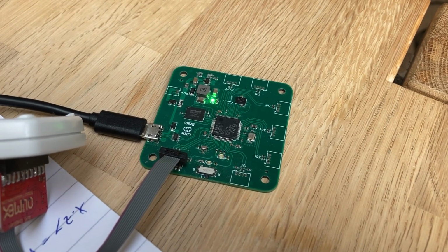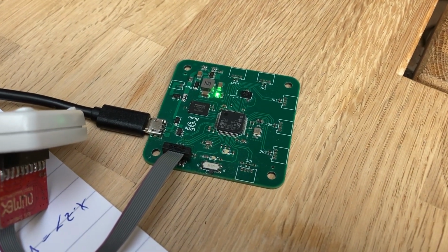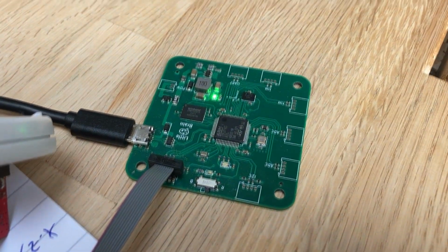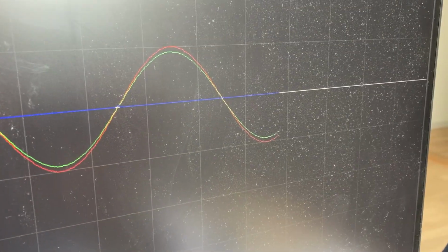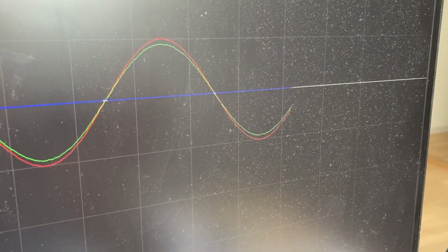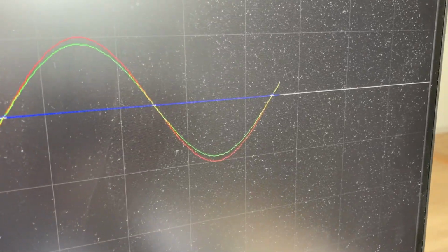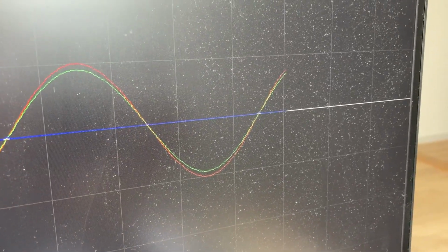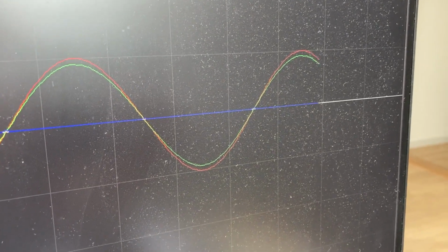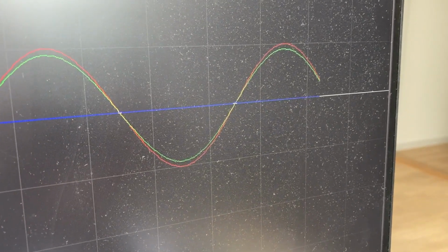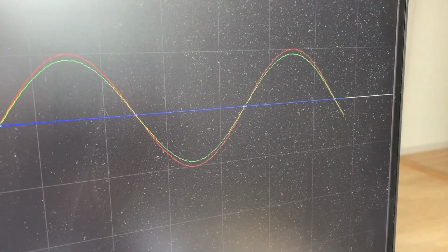So I've uploaded the code via the ST-Link to the LittleBrain board. As you can see, the code is running, the LED is flashing, and here I have my serial oscilloscope plotting the input-output data. As you can see, of course, the sample rate is quite low just to make sure we can see what is going on. But as you can see, for the input, which is just a simple sinusoid, the filter is essentially doing its job, and not being unstable, which is what we predicted for those alpha and beta values.